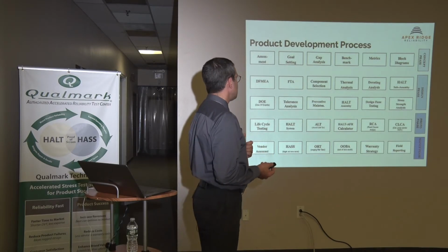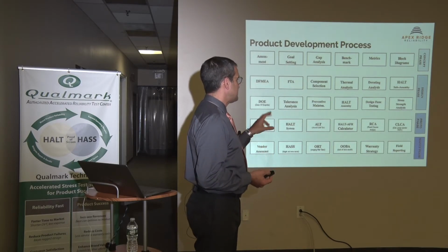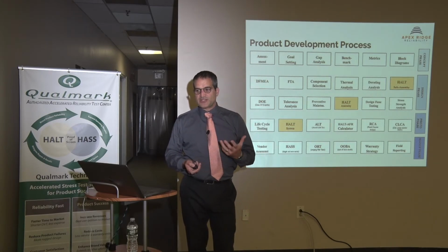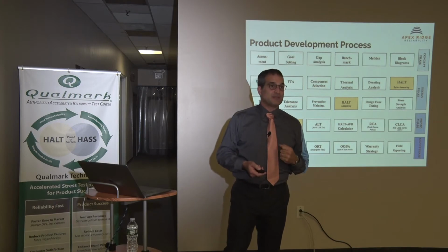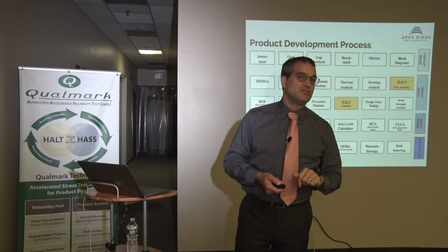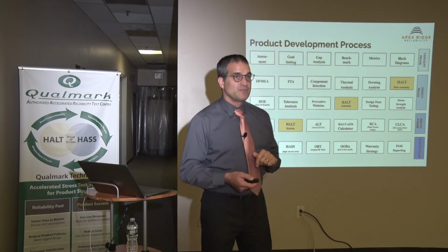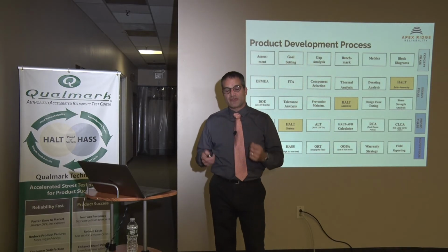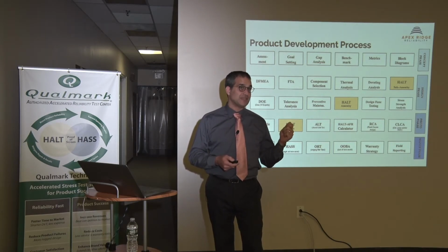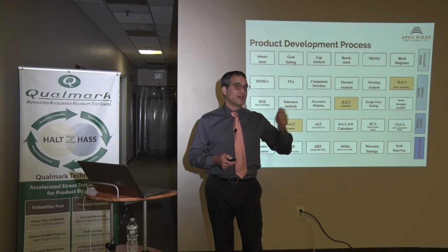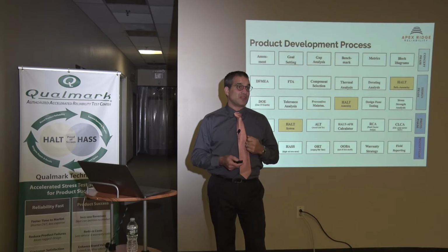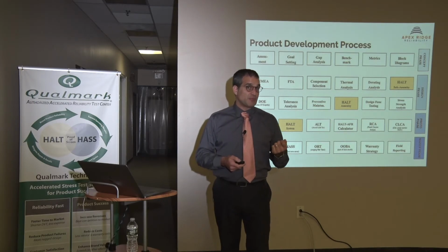These are all reliability tools that you might include in the concept phase, design phase, proto phase, or manufacturing phase. So you can see I actually listed HALT 3 times in there. Remember, HALT's a circular process. You want to keep using it. You want to continue to get this information about the product with regard to how it reacts to stresses and changes that have been made in the design, because there are changes that have been made in the design that are driven by other initiatives like cost reduction, manufacturing, maybe last-minute feature adds or removal. And this can affect performance.